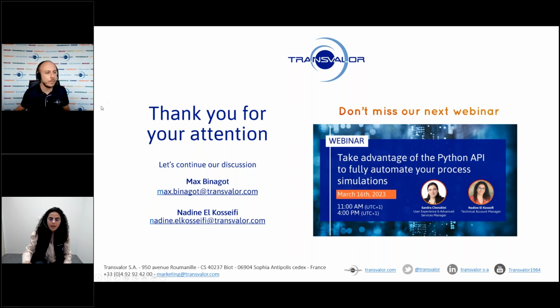Again on shearing, what does the new algorithm do differently? How does it work compared to the kill element? Both work with damage criteria first. You need to compute the damage criteria and define a trigger value. As soon as one element reaches the trigger value, the old algorithm was deleting these elements to split or cut the mesh in two bodies.